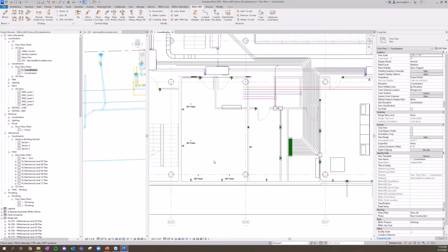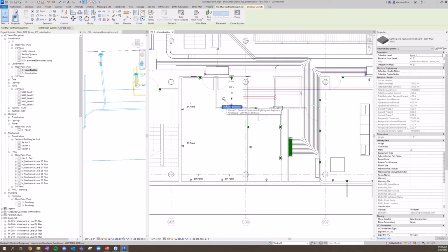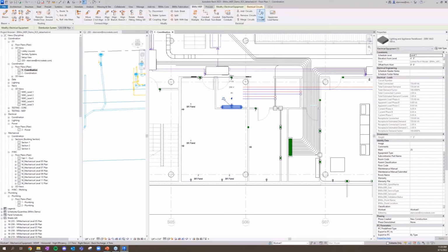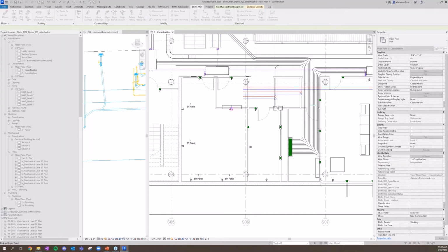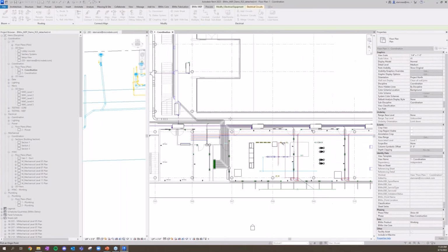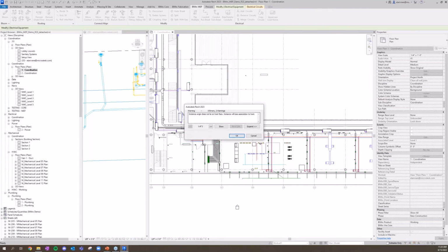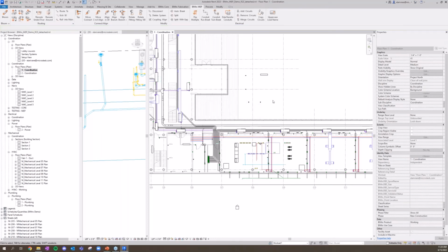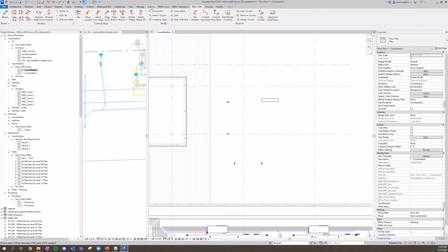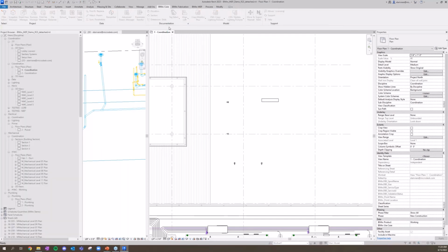Because what I'd really like you guys to notice is I do have some circuiting set up, and these are all circuited to this panel. We have an incredible command in MEP called copy circuits. If I copy circuits, and by copying them, choose a panel to copy the panel, I can actually put that anywhere I would like. We'll notice it's breaking host, but it's copying each group of elements with me. Not only did it copy those circuits, it also, let me go ahead and use tag select this time, so I don't need the settings window open if I have default set.